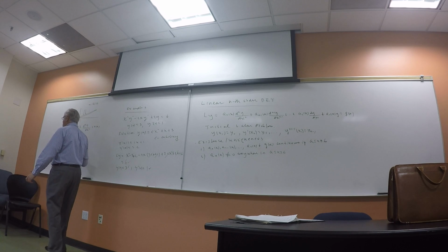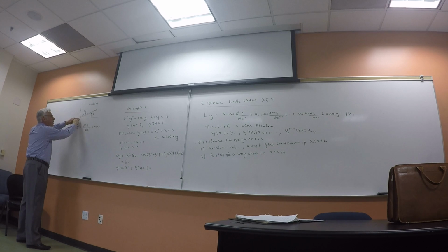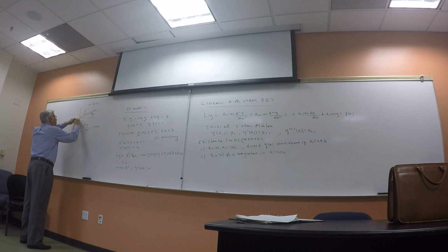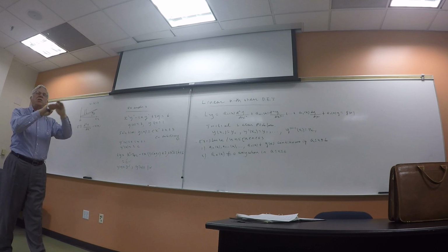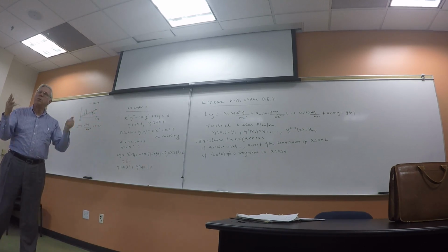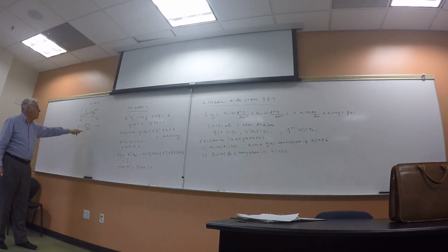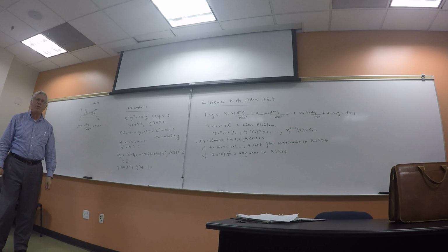Let me just tell you a little bit about what the coefficients are. y would be the deflection of the beam from the initial position. So the beam is straight over here, unstrained, just going between say x equal to 0, and maybe this is x equal to L, where L is the length of the beam when it's unstretched. And then someone puts a loading on it. It's obviously going to deform. This is the static case, so it's in static equilibrium, but obviously it's deformed because there's loading on it. So W of x, you know what that is, that's loading per unit length. x is the coordinate along the beam between 0 and L, and y is the deflection of the beam. This is all small deflection theory.